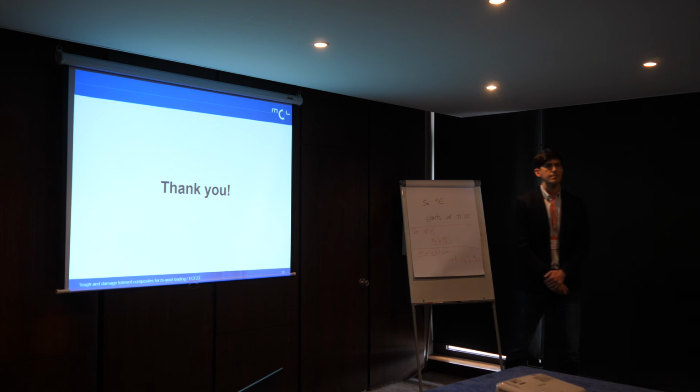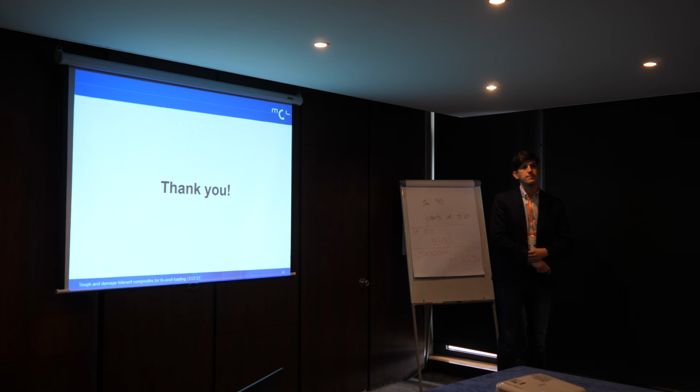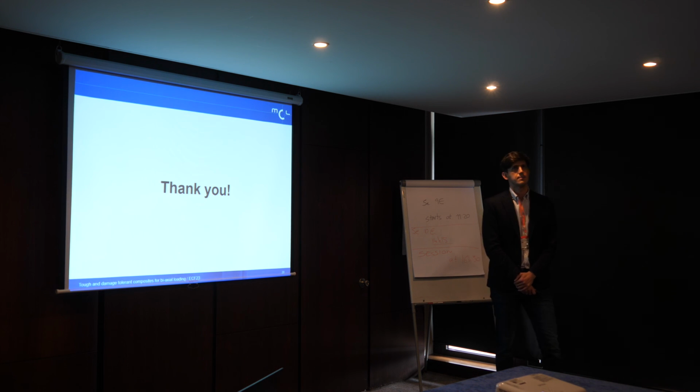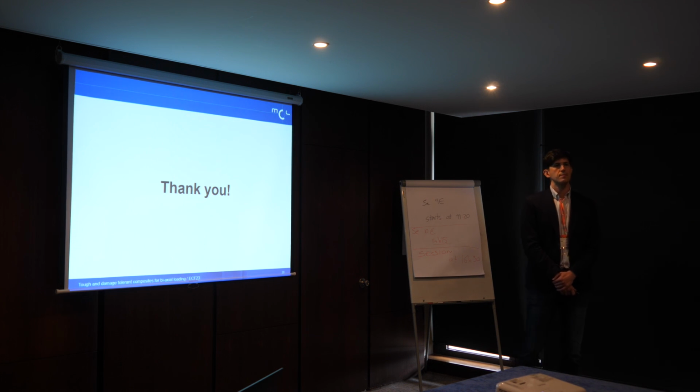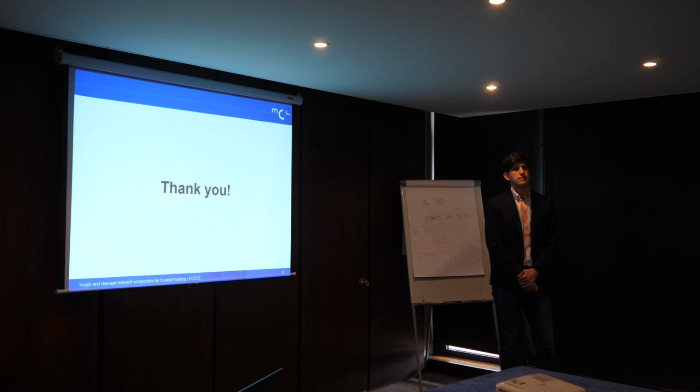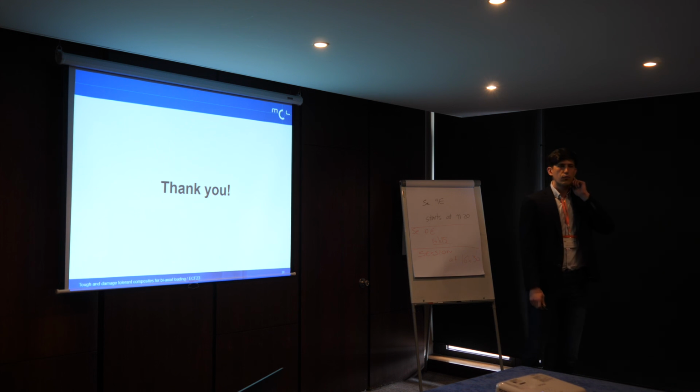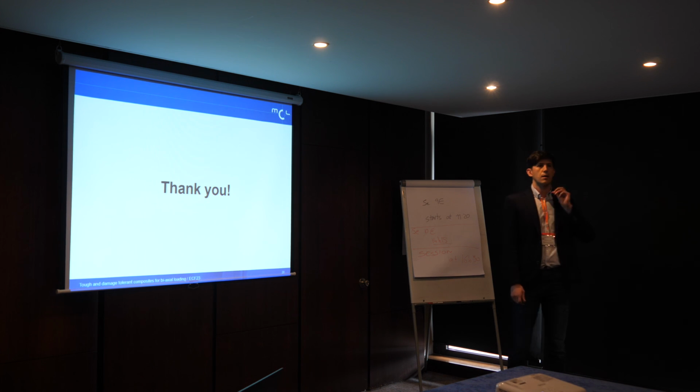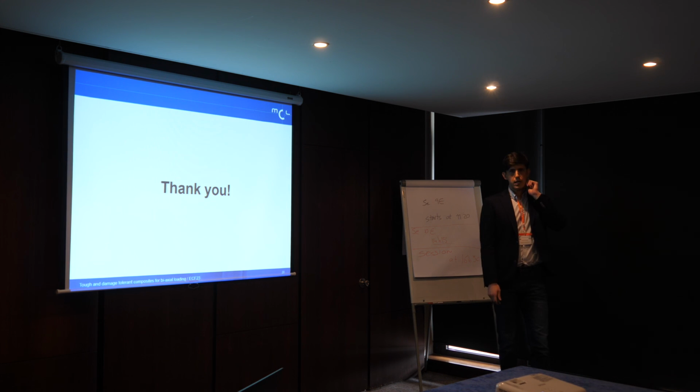A rather interesting problem, very nice results. But if you think of the forming of the crack, if you have a void, the stress concentration is about 3, on a free surface it's 1, so if a crack forms, it will definitely form in the void. So I cannot imagine a situation where the crack forms at the free surface and not in the void, because if you think of fatigue, that is where the crack forms in the beginning.